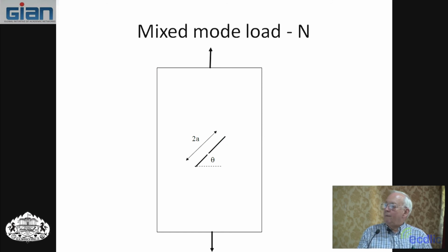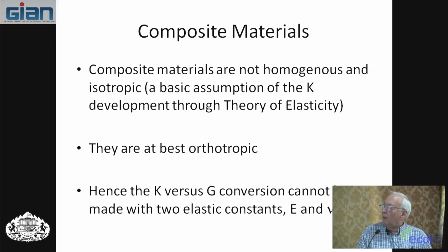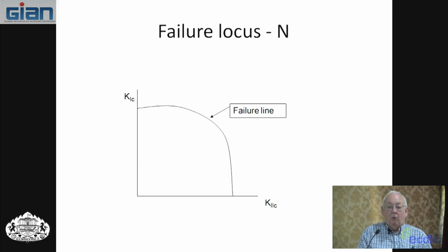The mode 2 specimens people used, trouble is if you have a pure mode 2 and you load like that, you get an unbalanced moment, you get funny moments. So people make a 2-crack specimen and they pull the middle and pull the outsides or whatever. So that's it for mode 1, mode 2 loading.